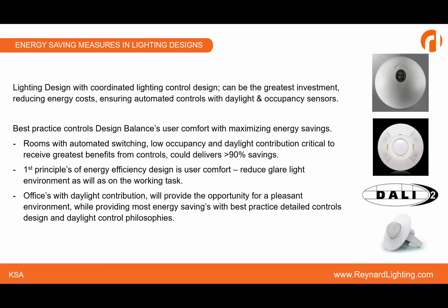And these daylight sensors will be connected to my luminaires. My luminaires will have DALI drivers. So when there is sufficient daylight penetrating, my luminaires will dim down to the required lux level.